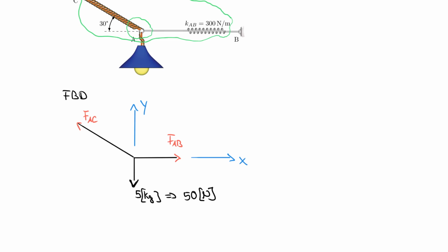All right, of course, I need my components. There's only one sloped member here, so only that has actually components. So let's add those. And I, of course, need also directions and names for those. Remember all the rules that we have. So FACX and FACY. Last but not least, I need my angle, which is right here. Let's call that alpha, or actually that's 30 degrees.